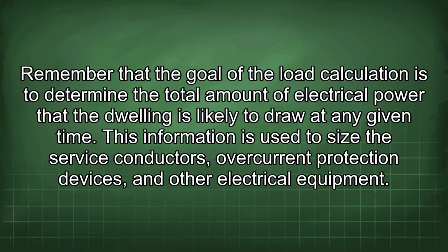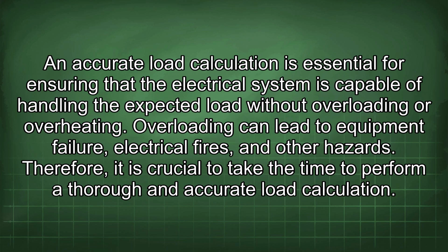Remember that the goal of the load calculation is to determine the total amount of electrical power that the dwelling is likely to draw at any given time. This information is used to size the service conductors, overcurrent protection devices, and other electrical equipment. An accurate load calculation is essential for ensuring that the electrical system is capable of handling the expected load without overloading or overheating. Overloading can lead to equipment failure, electrical fires, and other hazards. Therefore, it is crucial to take the time to perform a thorough and accurate load calculation.